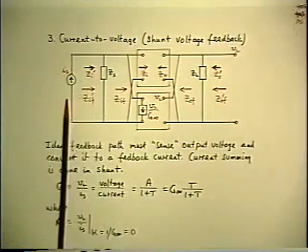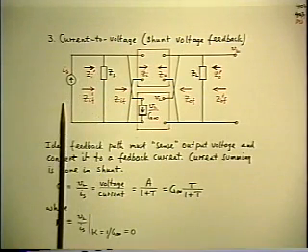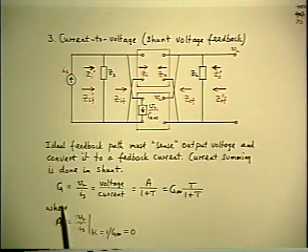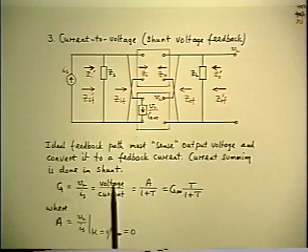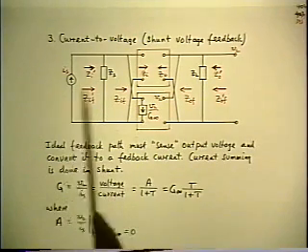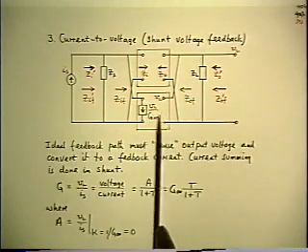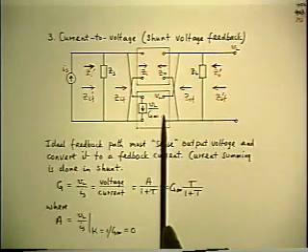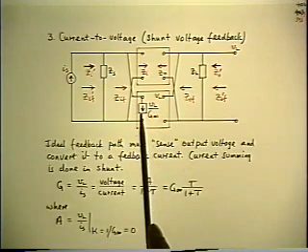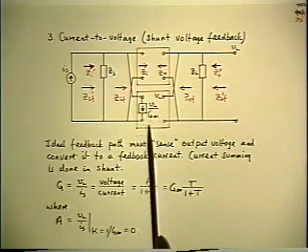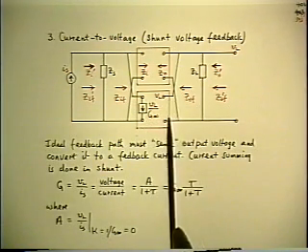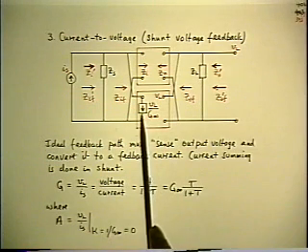But this time the input signal is going to be a current instead of a voltage. So the requirement is G is a voltage over a current, namely a transimpedance. So the G infinity must be a transimpedance. So the K must be a transadmittance, upside down. So the K box has to sense the output voltage and convert it into a fed-back current.